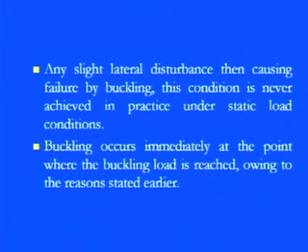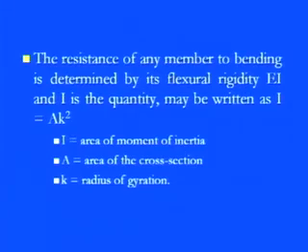whatever the reasons are, due to geometric nonlinearity, material nonlinearity, or when the forces are not exactly on the same axis and due to that eccentricity is there, all these are the key reasons through which we can say that buckling will certainly happen to the strut part. So you see, the resistance of any member to bending is determined by its flexural rigidity.